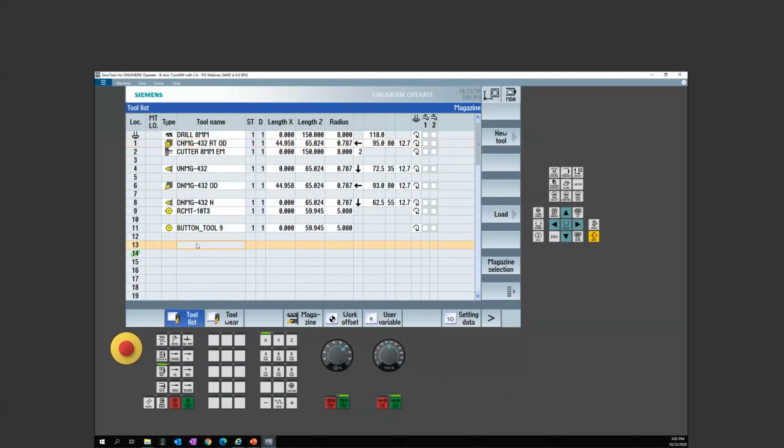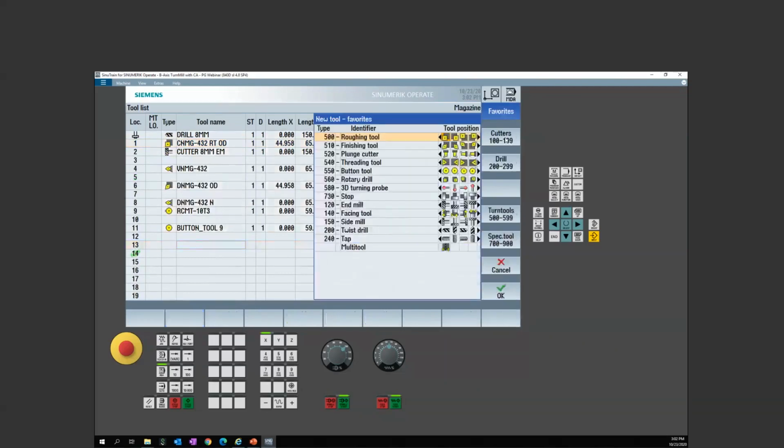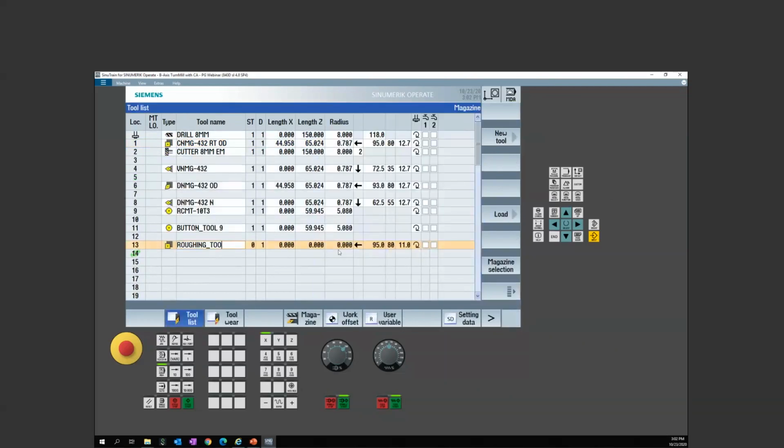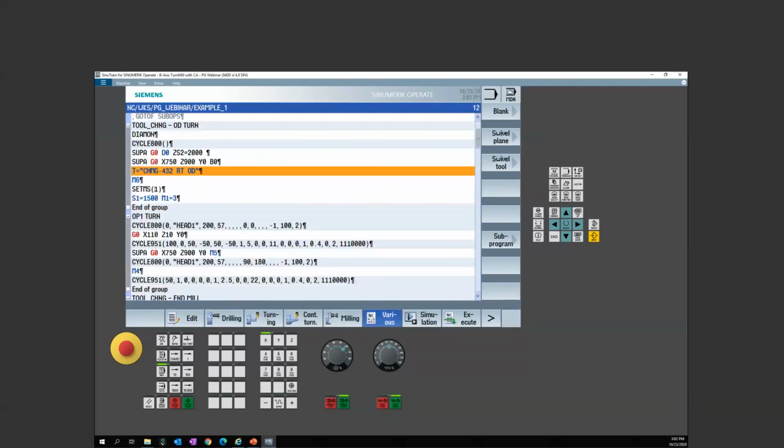If you want to drive based on numbers on this type of machine, then I need to name the number. Where on a regular turret lathe, I can drive it based on the turret location. So that's just a little difference that I want you guys to make sure you're aware of. Map your spindle, fire her up, and we're ready to turn something.